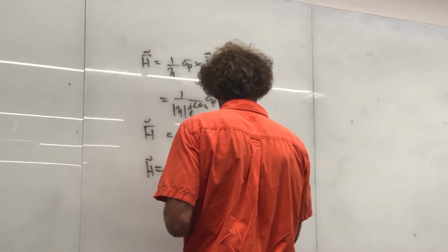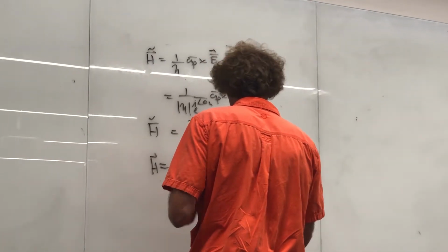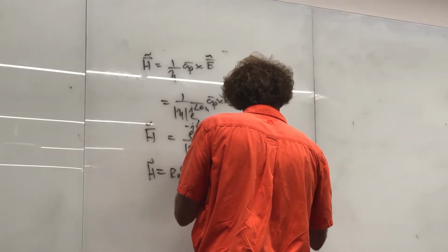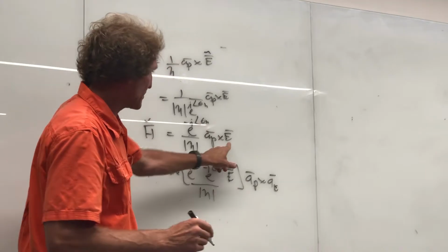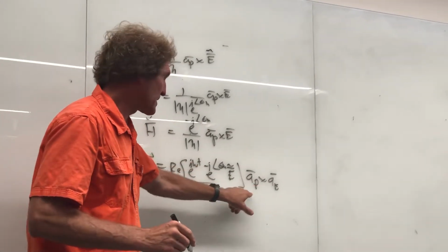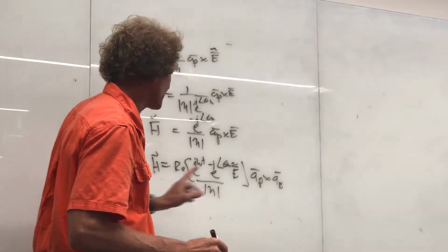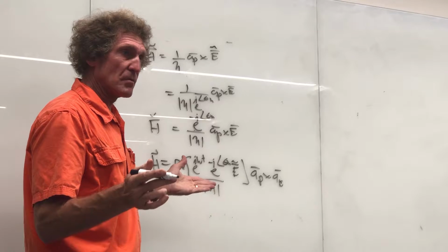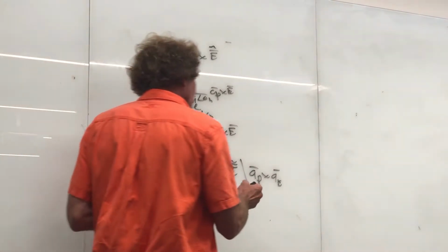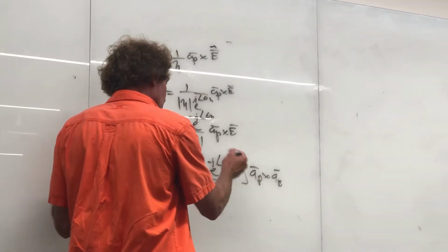And what I can do is take the E field phasor and just leave it in here, and then take the product of A rho crossed into a unit vector in the direction of the E field. See, I can take the vector sense of the E field and take it outside that real part. Are you with me? So this gives me the direction of propagation, or excuse me, the orientation of the H field, dependent on the E field's orientation. But the actual information about the signature, the time varying signature and the decay is right in here.